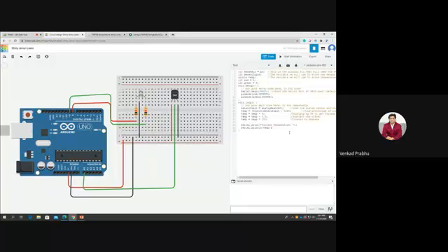And followed by that, at the bottom here, I am going to check the condition if temp is greater than, for example, 50°, and inside that I am going to make digitalWrite of red comma HIGH, and digitalWrite of green comma LOW, which means red color is going to be high when the temperature is greater than 50, and I am copying it, and else the temperature is normal.